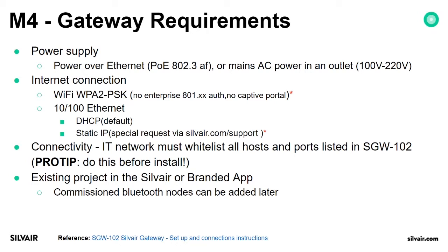It's important because sometimes it takes even 2 or 3 weeks for IT support to whitelist all important hosts and ports. Most of the time we see that after commissioning all the nodes, the customer goes to the project with the gateway, connects the gateway, and it's not working because the network is not prepared for it.